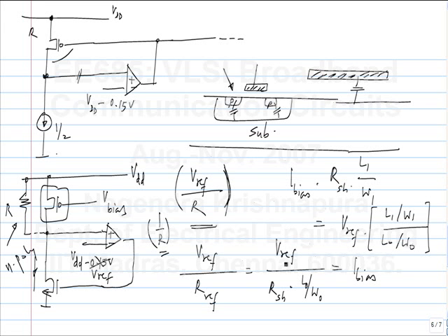If you have resistances of different types, which have no correlation with each other, maybe you have an N-type poly resistance and a P-type poly resistance, then of course you need to make a 1 over R bias generator for each type. Because if in the reference generator you use N-type poly and then you pass it through a P-type poly resistance, the sheet resistances are different. There is no reason to assume the same temperature dependence either. So they will not track, but as long as you stick to the same type of resistances, you can propagate currents which are inversely proportional to that type of resistance and pass it through resistance to scale the voltage.